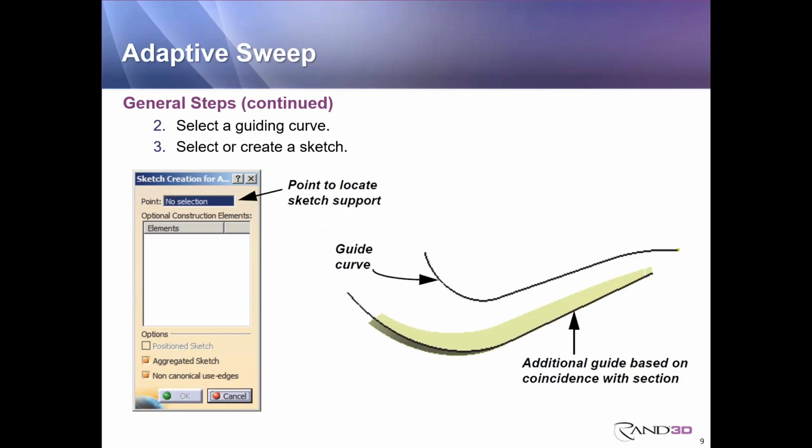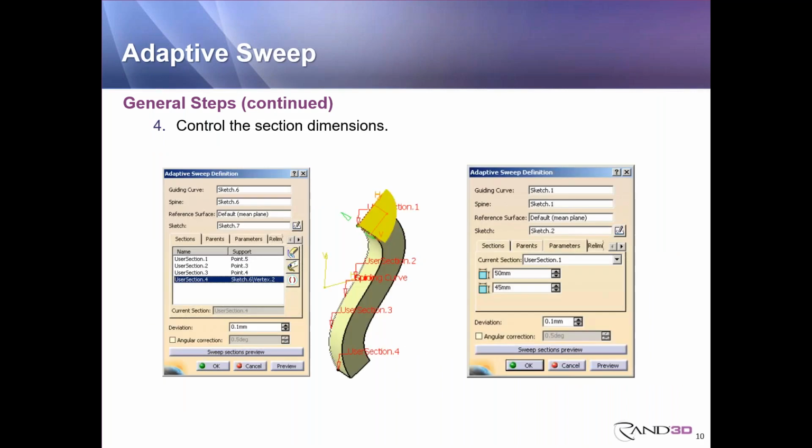From here, this gives you an image of the sketch creation environment when you are defining your points on the fly. You can do that, or you can do what I did and create your points as independent features so that they can then be selected while you're defining the sections at those points.